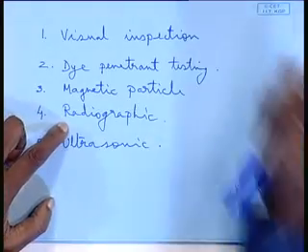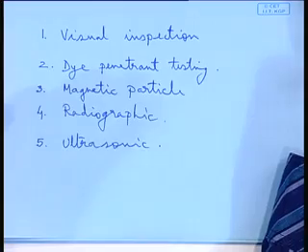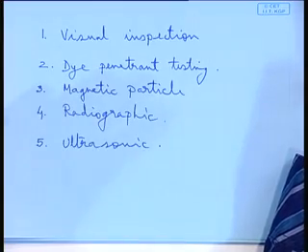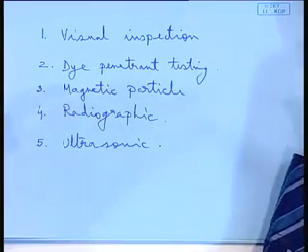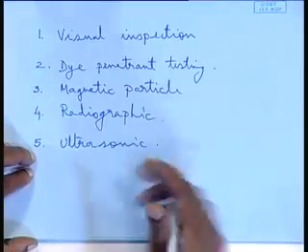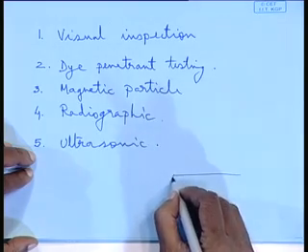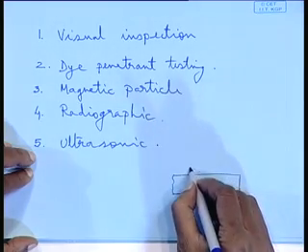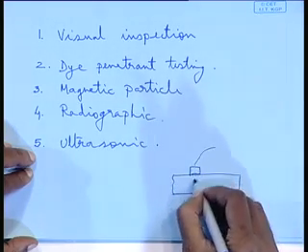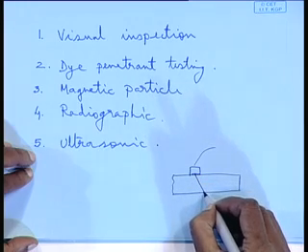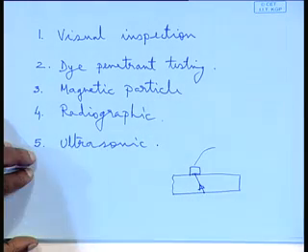Other disadvantage of radiographic is that it is hazardous. That is number one, very much hazardous, and second, it's a bulky equipment, so you cannot test in every nook and corner. Whereas ultrasonic testing uses the principle of sound. Whenever a sound wave meets an interface, it gets reflected.